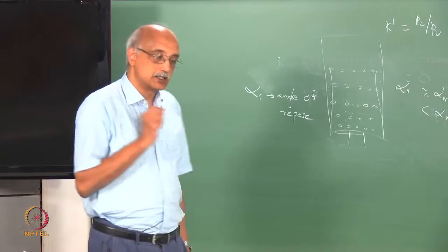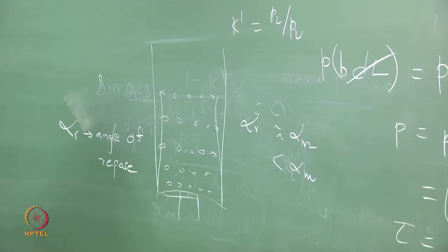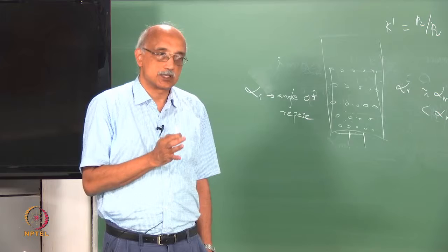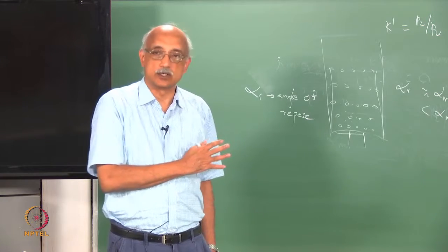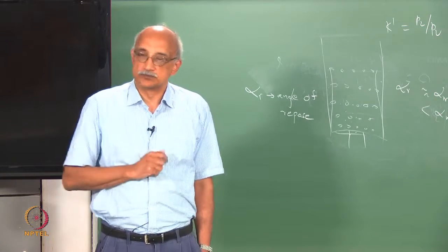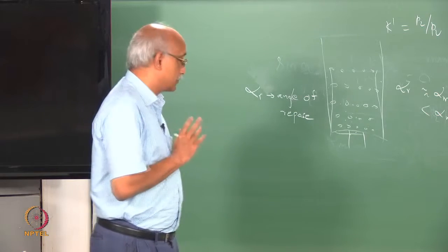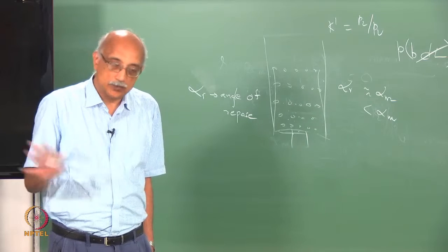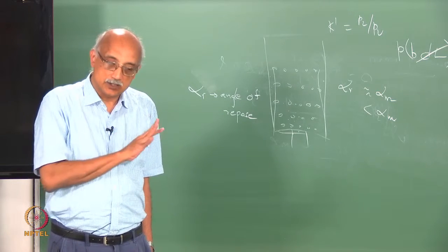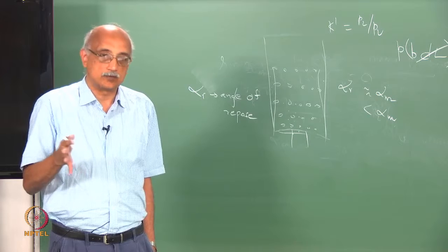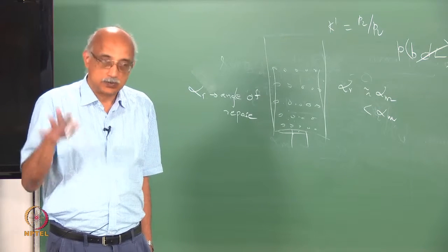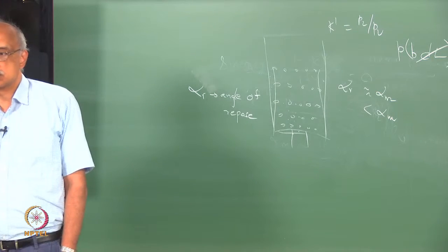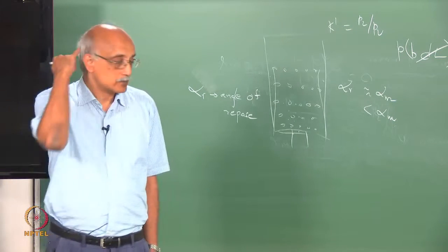Essentially the way you can look at this is, the higher the angle of repose, the easier it is to dislodge the particles from the surfaces they are in contact with and have them start moving along with the rest of the flow. Whereas, if the angle of repose is 0, then it essentially says all the material is well lined up and well adhered to the surfaces that they are in contact with. It is going to take more time, more force to start them in motion.